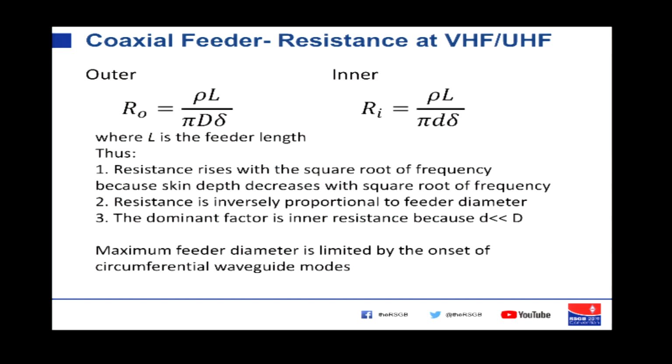That means the plating quality of things has to be superb, because if they're not very well plated, so the surface is rough, the actual resistance value will be way above the bulk resistance of the material. So people who are not very good at making connectors and don't have very good plating lines, they will have performance in their connectors way worse than you would expect from this. So now, on to